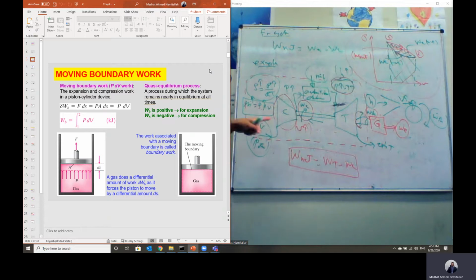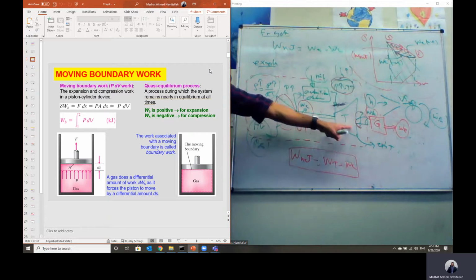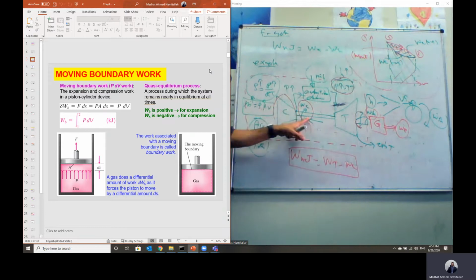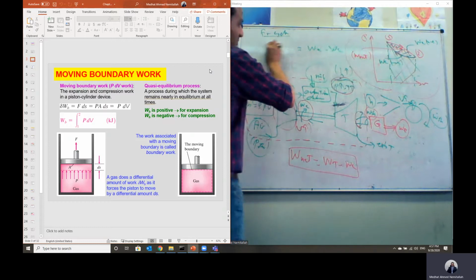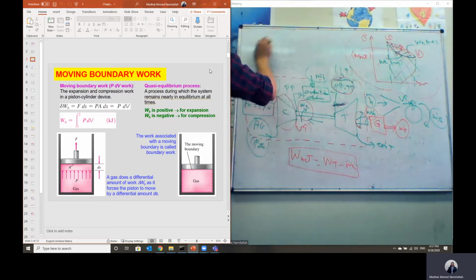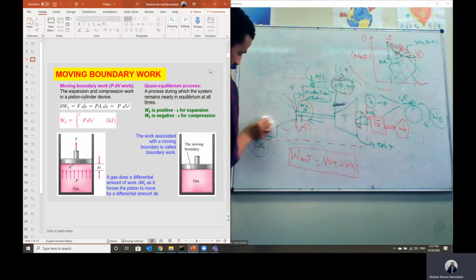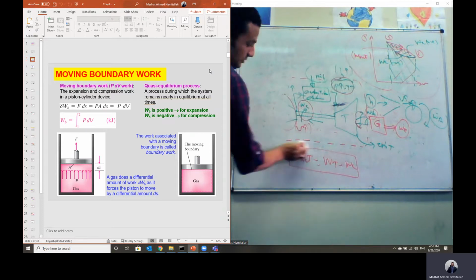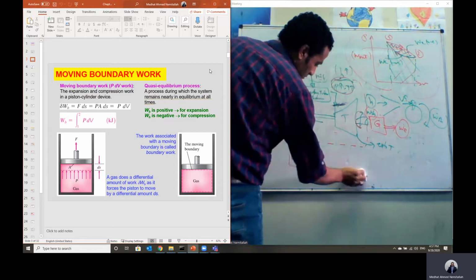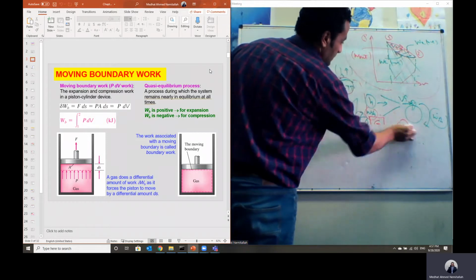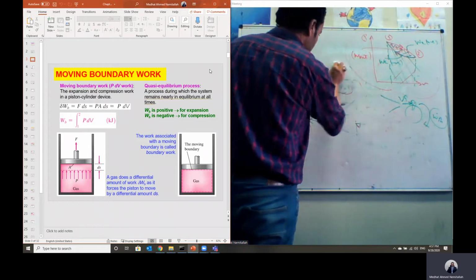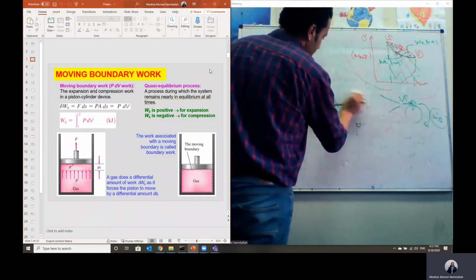So one drawback of the gas turbine is that part of the produced power of the turbine is actually used to run the compressor. This is in comparison to the steam turbine, which does not require a compressor. Because in this case the working fluid is liquid water first, and we use a pump with low input power to raise the pressure of water up to the boiler pressure.